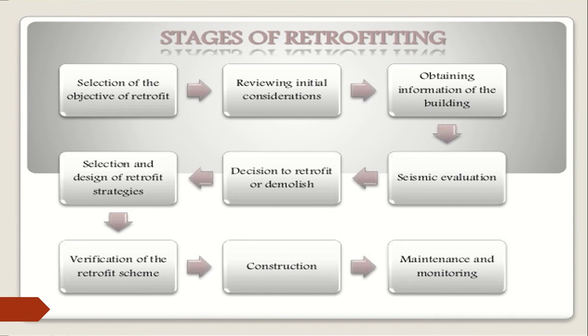In the seismic evaluation, we will be studying the damages which are caused to the building due to the seismic activity. Then we have to decide whether to retrofit or to go for a demolition or a complete replacement, etc. Then we have to select and design retrofit strategies. So certain strategies have to be imparted, like what has to be done next and what method could be adopted. That design of retrofit strategies is the next step. Then we have to verify the retrofit schemes. Then only we will move on to the construction, and after construction we will be monitoring and maintaining it properly.